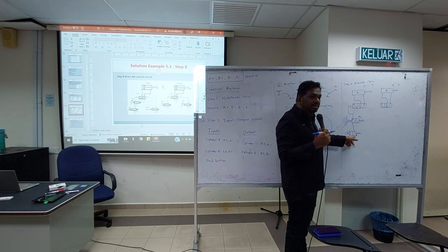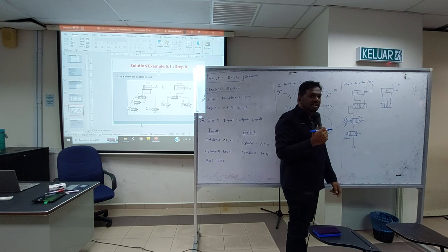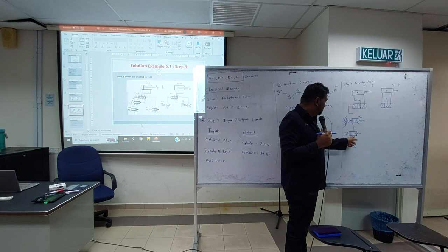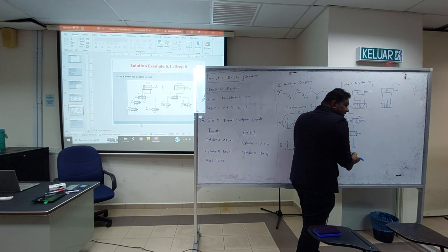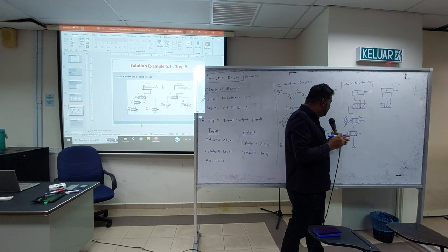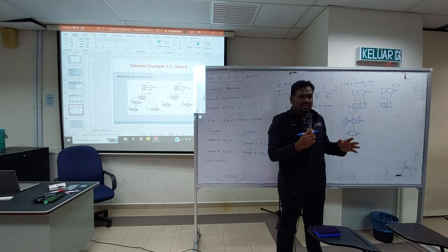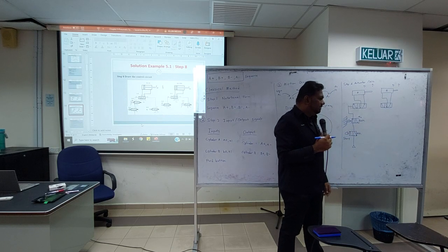So what will happen at port P? Is there a connection here? There is no arrow, it is disconnected, there is no connection. So before you press the push button, it is disconnected. Because the compressor goes here, it stops, it cannot go.